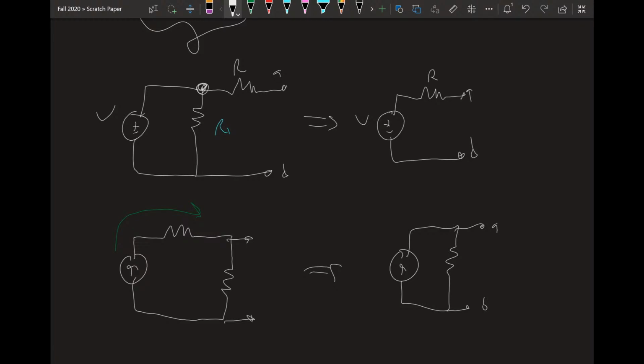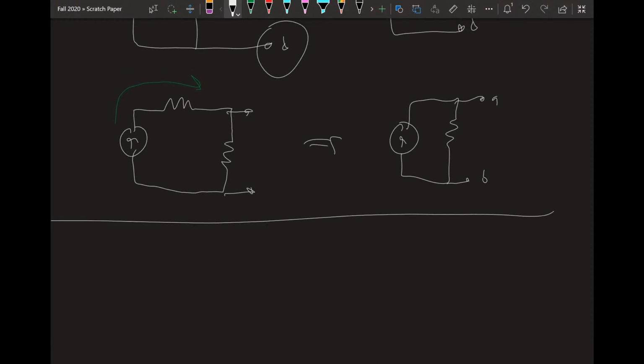Now, I'd like to stress what I mean by an equivalent circuit. I mean equivalent over the terminals A and B, nothing else. These have the same effect over those terminals, but if you talk about something not over those terminals, it does not have the same effect. So you have to be careful with how you simplify circuits using this, but it's still a powerful tool for your analysis. I have one example of how you start going through and analyzing it. So let's do that one example.